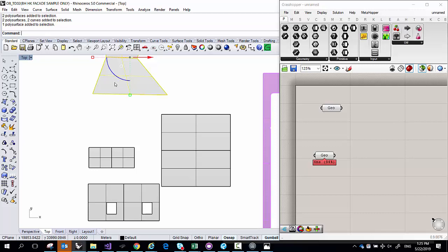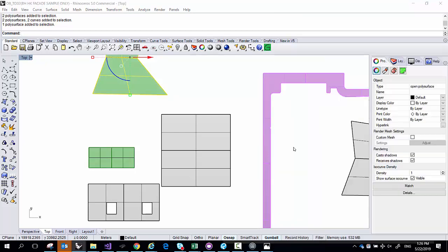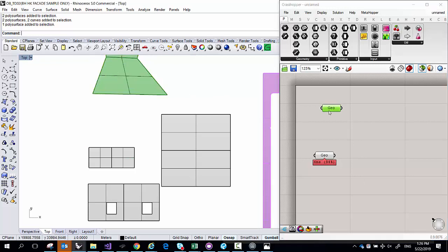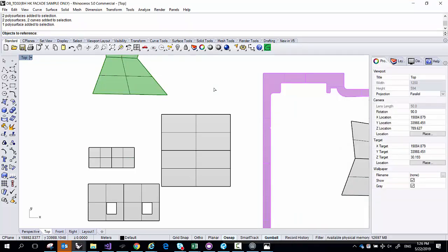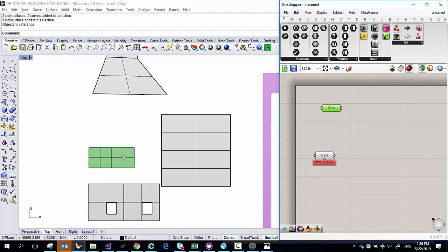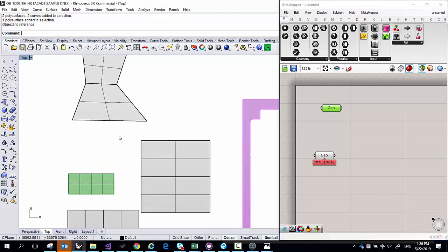Grasshopper, did you minimize it? Just type Grasshopper again. She's lost Grasshopper. So there's two things here. One, if you right-click here, Grasshopper will disappear if you don't have anything selected. Well, look at the command line here, just like in CAD. Look up at the top here: objects to reference. Grasshopper's got it out of your way nicely, so you can click something and then it comes back. So just click something and press enter.